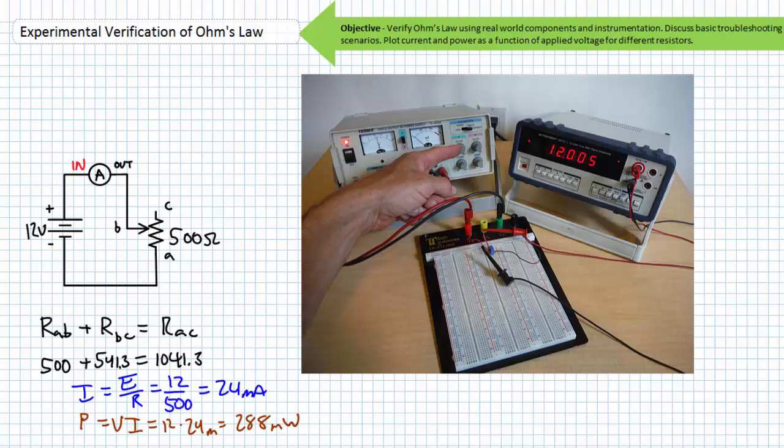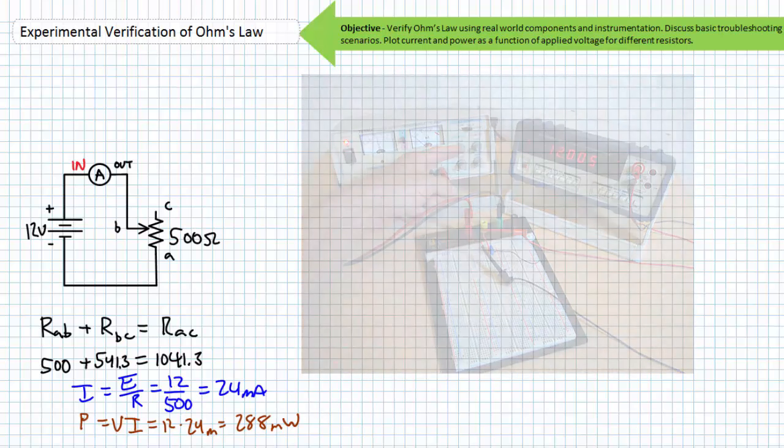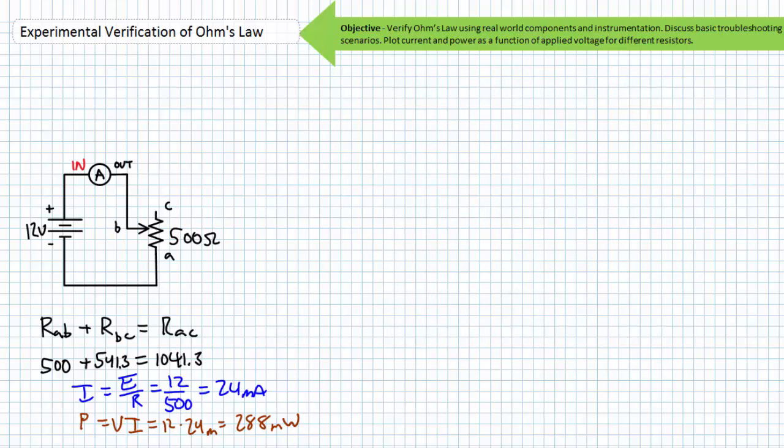This ensures that there's no damage to our equipment and we really are operating at known conditions. If we were to assume from either our initial analog needle meter measurement or our unloaded voltage measurement, we would not have been operating at 12 volts. With the wrong voltage supplied, our measured value of current would be wrong. Reality follows the GIGO principle. Garbage in, garbage out.